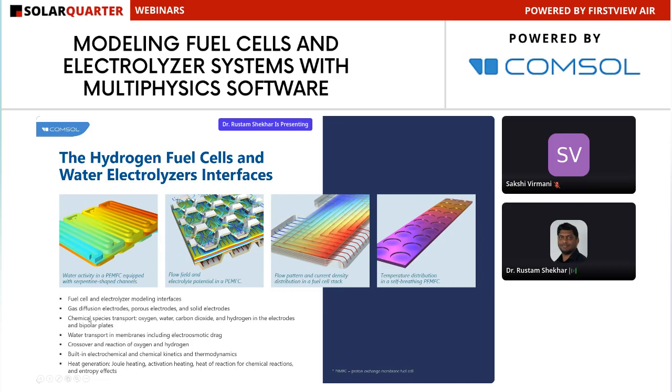Here you can see the bipolar plate and the electrodes both can host these kinds of chemical species. So you can solve for the chemical species in the bipolar plate, where you can have the flow channels, and in the electrode as well. In low temperature fuel cells, you will see one very basic problem, which will be water transport in the membrane. So you can include that as well, and species crossover, to see the losses of your active species, or else the voltage drop due to this crossover of oxygen and hydrogen.